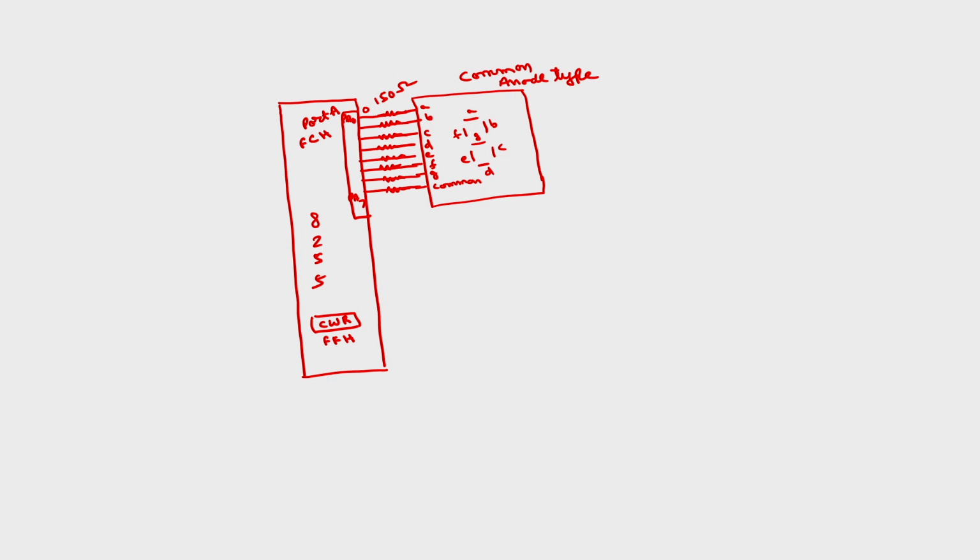Okay. This is interfacing. So, if I want to implement a decimal counter on this particular 7 segment display, it means first you display 0, then 1, then 2, and so on up to 9, then after 9 again you come back to 0 continuously, and you allow some time between 2 consecutive counts, say 1 millisecond or 1 microsecond, depending upon the application.